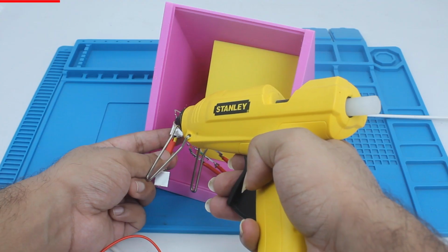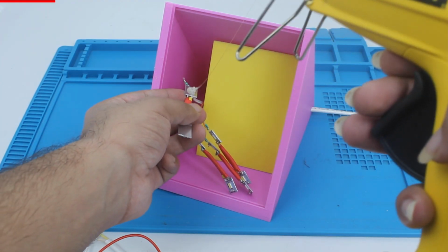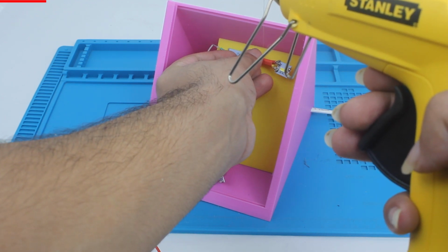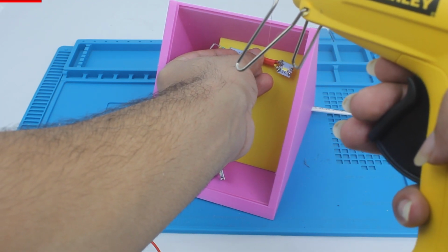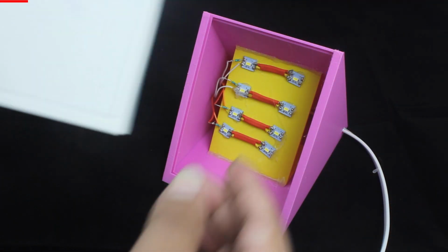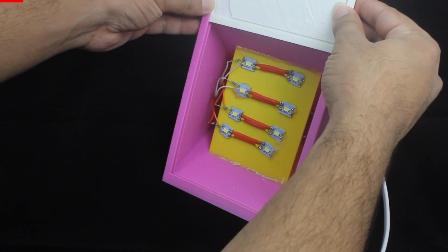I used a 2-core insulated wire and soldered these LED pairs onto it in parallel. I connected all of it to the USB cable and tested if everything was working as it should. I soldered the other end to the USB cable and then glued everything together, and voila, we're done. You put in your plate and your lamp is complete.